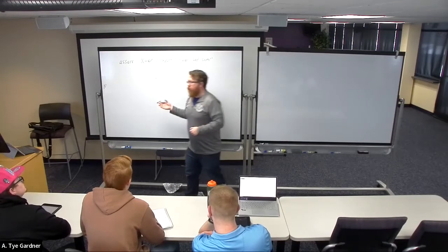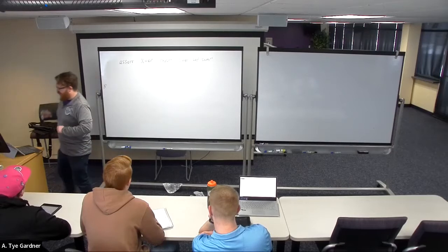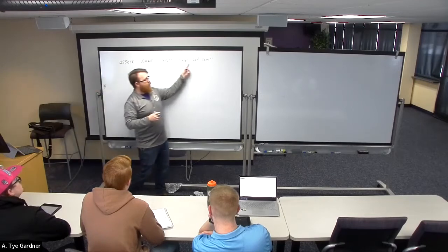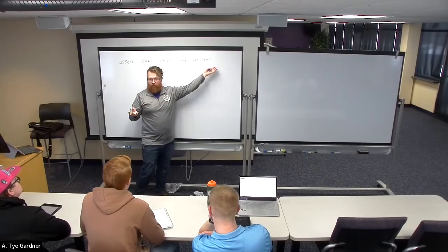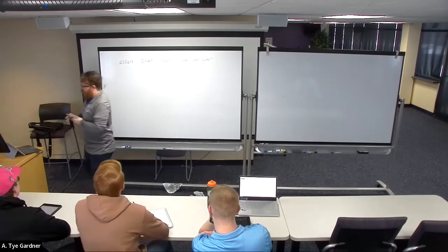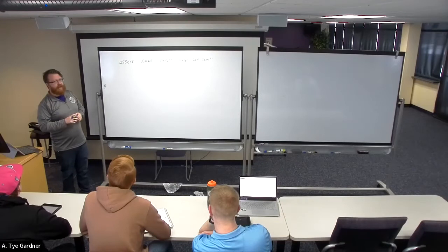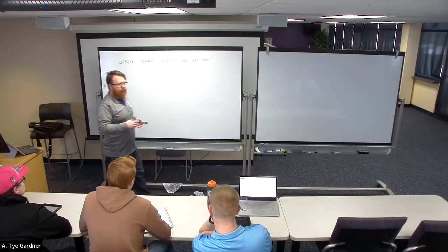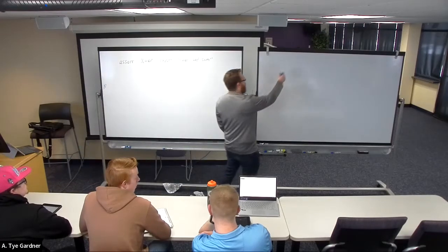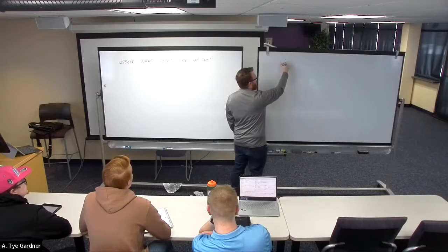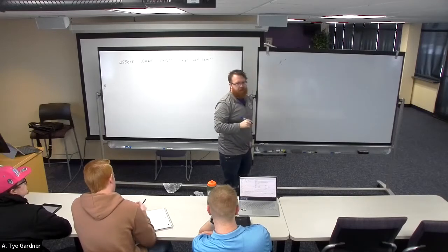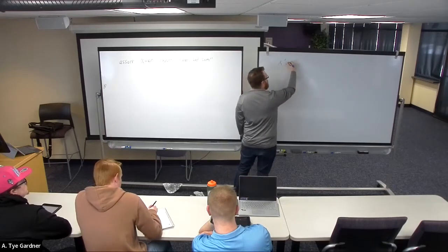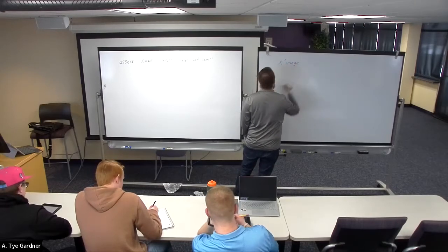Where am I, right? So we want to do something intelligent and make our reporting better. And we can do that by, inside of the report statement, saying what was the value that I had. We're going to do that by using what's called an attribute. The signals and data types that we have have attributes, and they're accessed with an apostrophe. So if I have a signal called x, I put a little apostrophe and then write what attribute I want. In the case of the value, what I want is image.